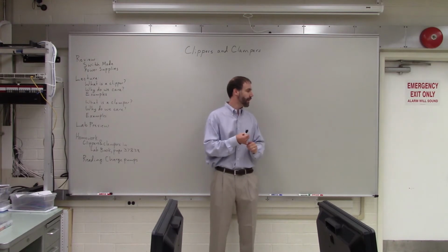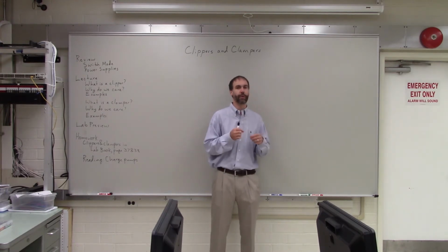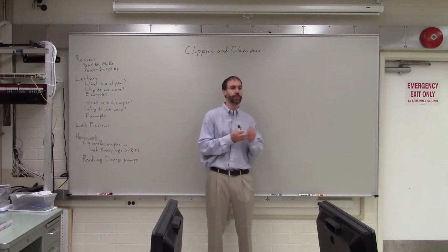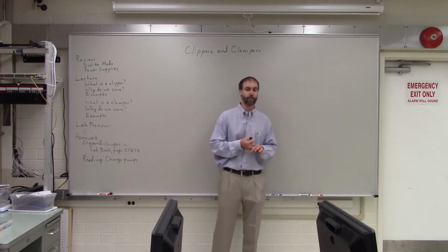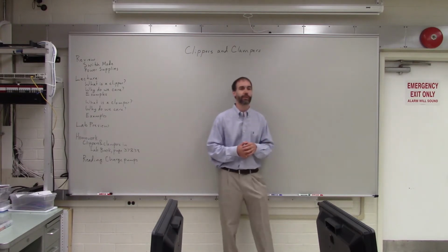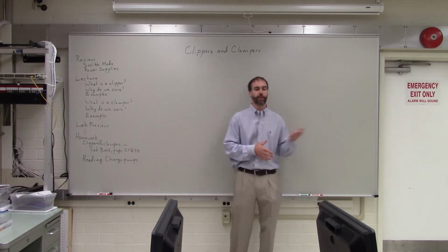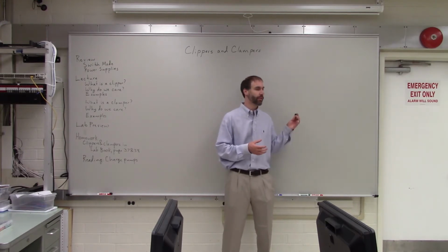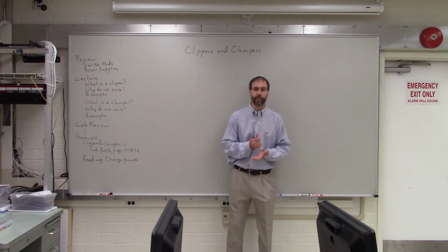So you could save size because the components were smaller. You could save money when you were constructing it because the components were smaller, and also it was more efficient. Remember, they said that switch mode power supplies were something like 80% efficient, whereas linear analog supplies were closer to about 50%. So you get a big efficiency advantage.